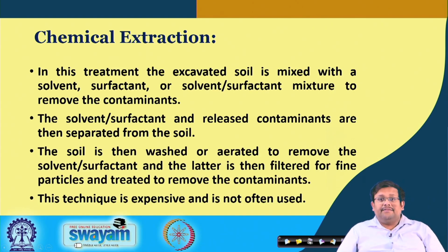The next method for ex situ soil treatment is chemical extraction. In this treatment, the excavated soil is mixed with a solvent, surfactant, or solvent-surfactant mixture to remove the contaminants. The solvent or surfactant and released contaminants are then separated from the soil, and the soil is washed or aerated to remove the solvent and surfactant, and the latter is then filtered for particles and treated to remove the contaminants. This technique is expensive and not very often used.